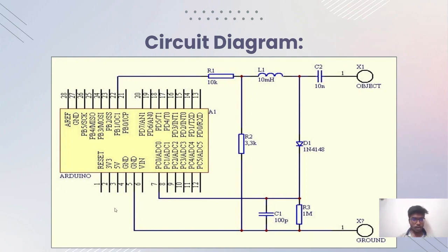If you see here, the ground is connected to pin 5. And this port number 9, which is pin 22, is called the PB1 OC1A pin. This is especially used to generate precise PWM waves, which are internally connected to timers. These precisely generate square waves, but to our concern, we can't use these square waves directly.